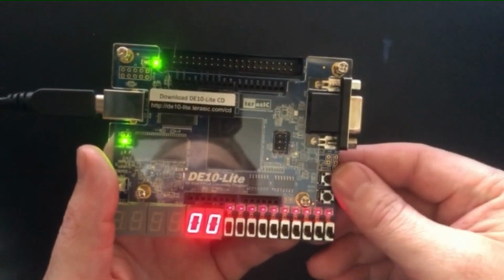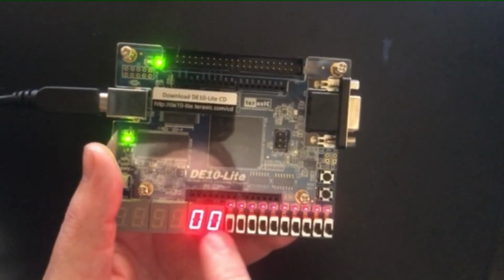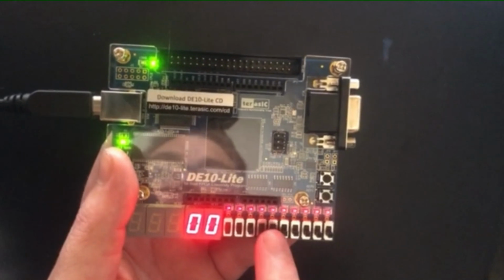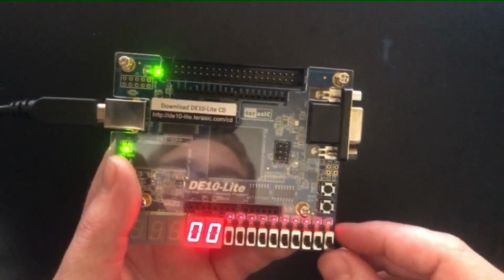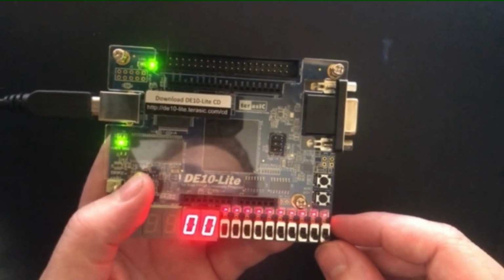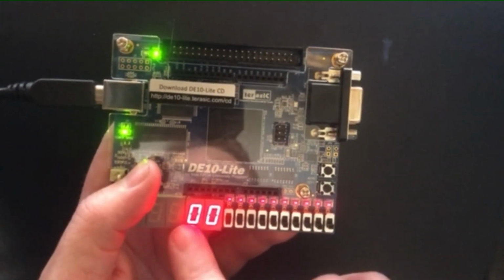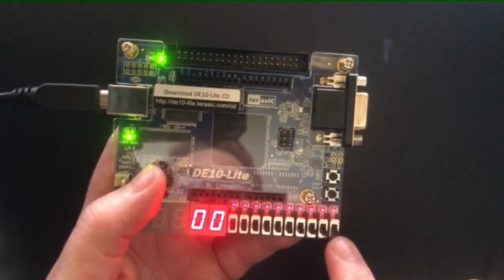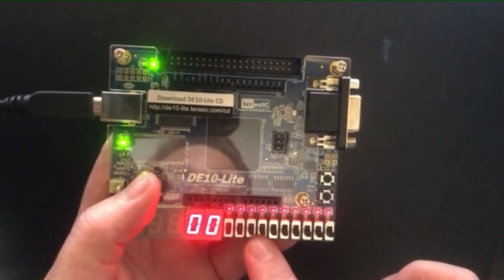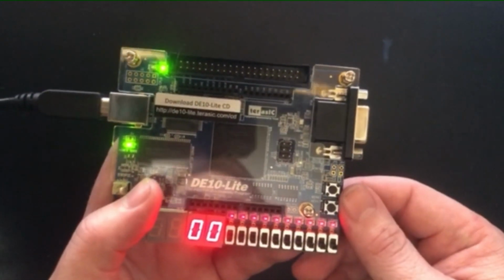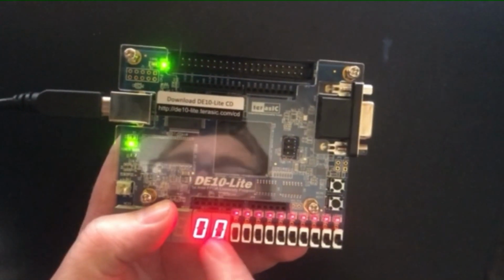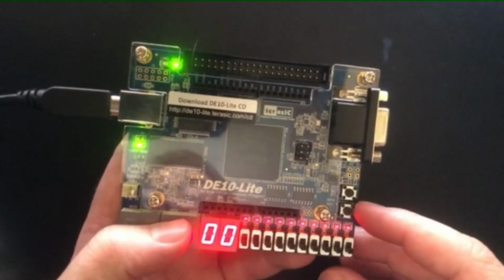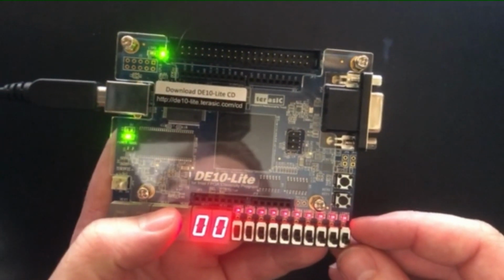Alright, and here is Lab 2, Part 1. We have hex 0 and hex 1, and I do believe I actually have them backward. I mixed up the pins. I wasn't paying too close attention to the numbers, but if we want to play with hex 1, we'll be using switch set 0 rather than switch set 1. I'll make sure I flip that around for the next demo. But nonetheless, we can control each of these 7-segment displays independently, and we will do so just by doing this.